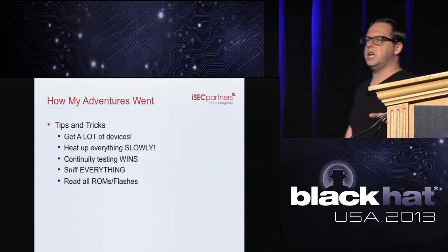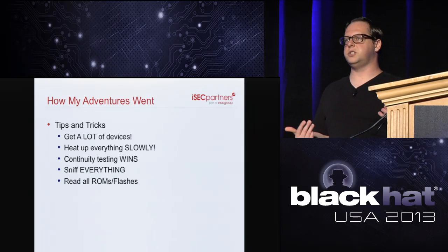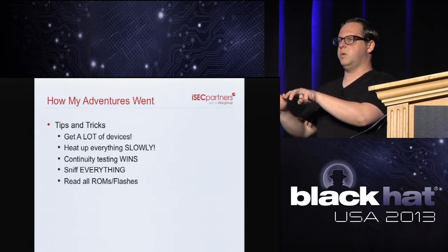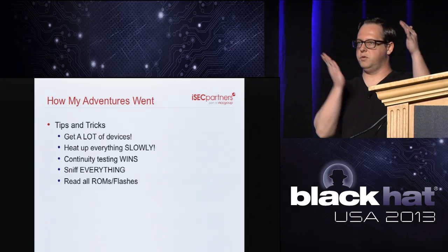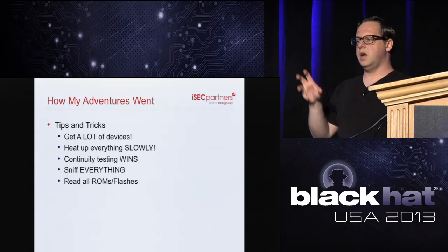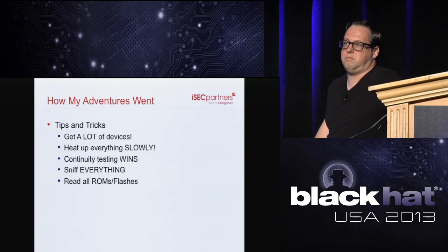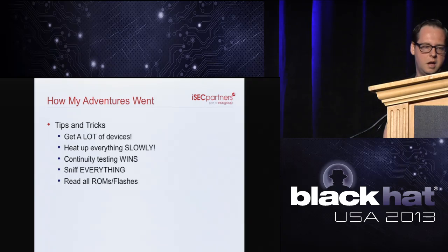I only had an 8-channel logic analyzer, so I picked 2 reference channels, which were the UART ones because they started first, and I said UART lines, 6 wires, UART lines, 6 wires, UART lines, 6 wires, and then I kind of grouped them all together so I had a reference. And read all the ROMs and flashes that you have, and pull out interesting information on that.